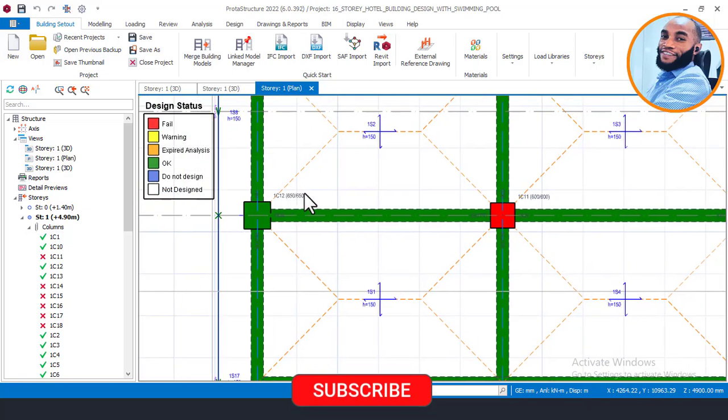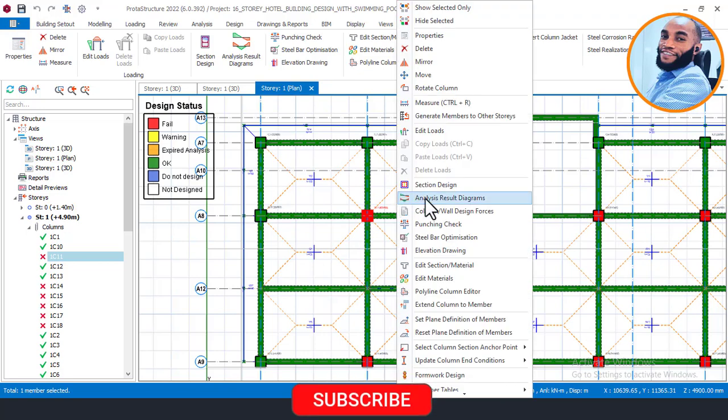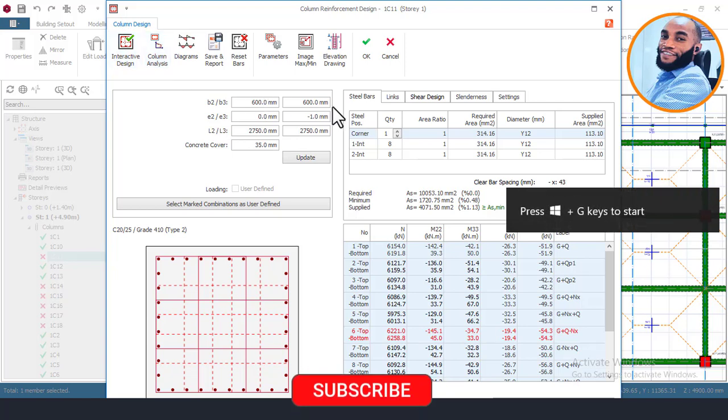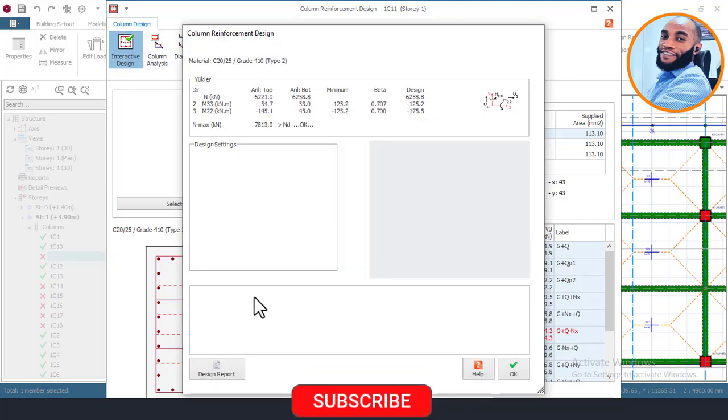So with this idea, I'll go again and check this other one too by clicking on the column here, and then clicking on section design here, and I'll hold on again for it to show. I'll not just go and increase the size first. First of all, look at what is causing the failure. So always click on this section design first and wait for it to show the warning.